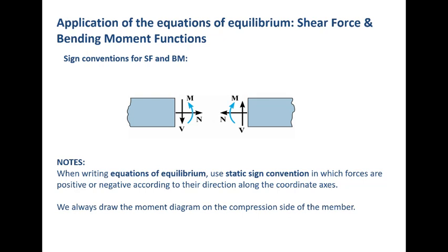But the slab under me that I'm standing on is resisting my weight. How does it do that? By deflection. So the beam or the floor under me, even though I may not feel it, there is always a level of displacement. So it bends a little bit, then it's engaged.